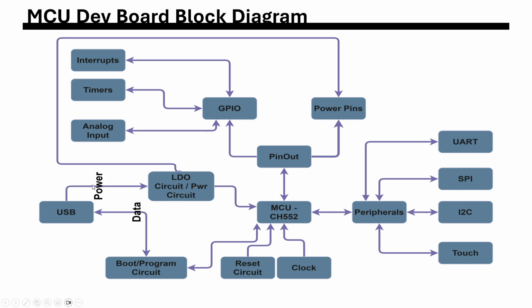The voltage from the USB would be transferred to the internal LDO of the microcontroller, which would supply all the functions of the microcontroller, right? The USB connector will also carry the data pins which would be sent to the microcontroller. We need to have a way to reset the microcontroller. We need to configure the microcontroller's clock if it is external. Here it would be internal, so we can do it via software, or basically the bits for that particular clock.